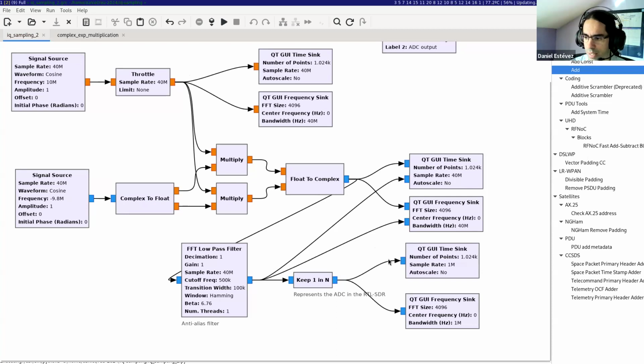Each of the two real numbers in the complex number, so the real part and the imaginary part, comes from multiplying the radio frequency signal on the antenna, which is a real signal because it's a voltage from the real world, by two local oscillators which have the same frequency and have 90 degrees phase difference. So we might think about it as a complex local oscillator, but just as a shorter mathematical representation for it. And then we have done the multiplications and assembled everything as complex numbers.